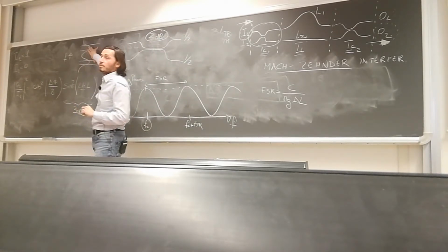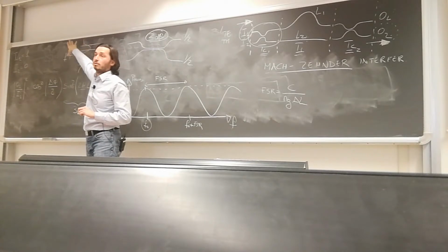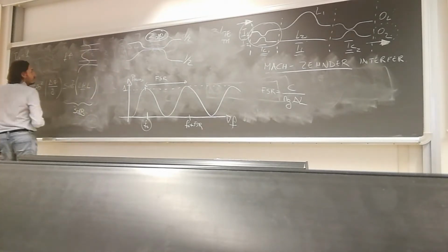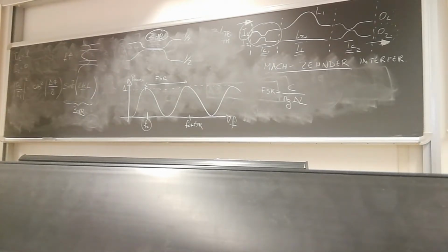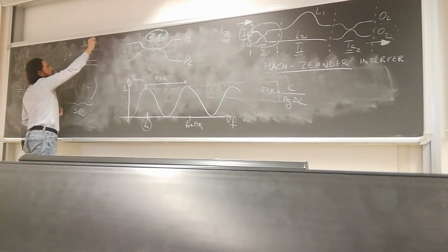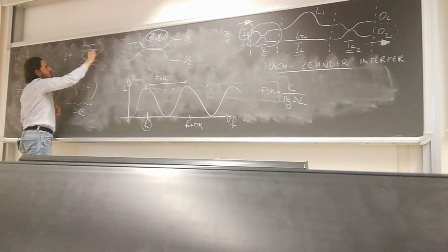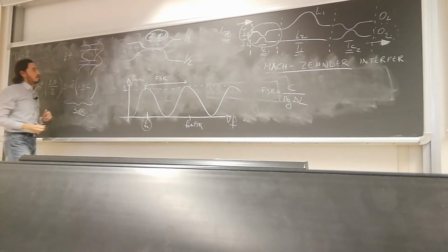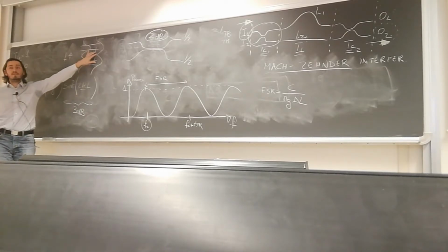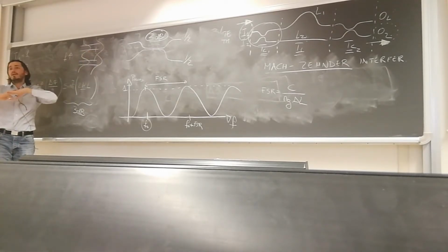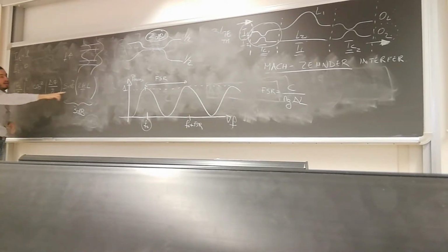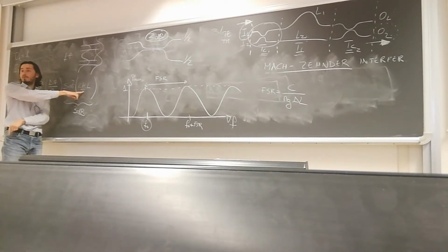So the waveguides are the same, they do not change. So if I tell you, okay, I increase the frequency, and the mode is going to become broader, like this. So if I make this design, it means that there is higher overlap, and so if there is a higher overlap, K is going to be bigger or lower?